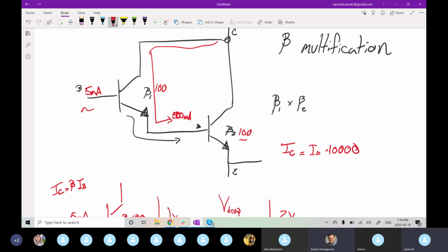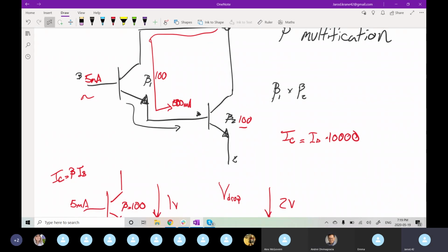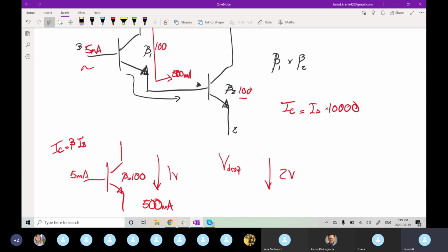Is the Darlington pair used in any of our boards, like the power distribution or anything? No. The power distribution uses a buck converter. Just the buck. Okay. It may internally, because I think some buck converters will use transistors instead of MOSFETs to do their switching, because the operation is just switching.